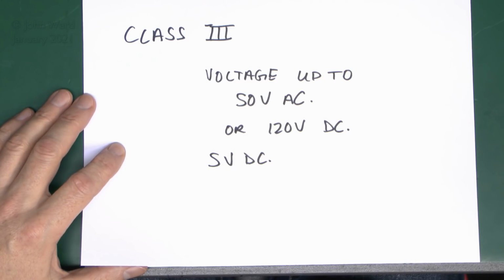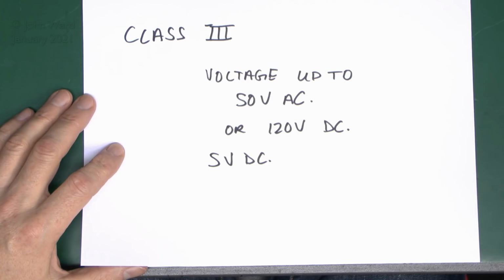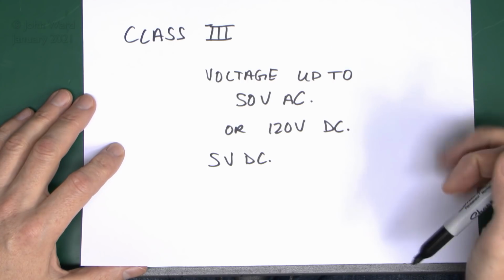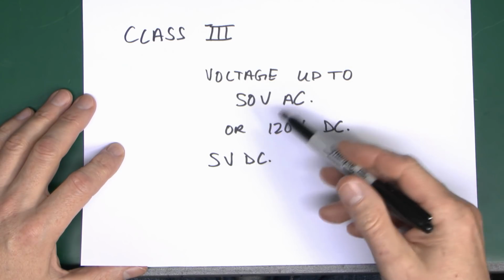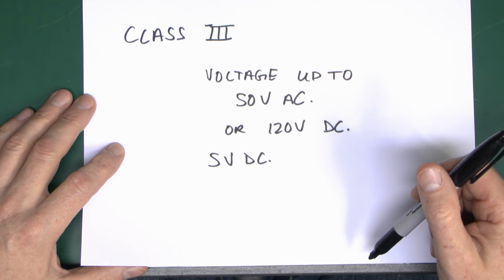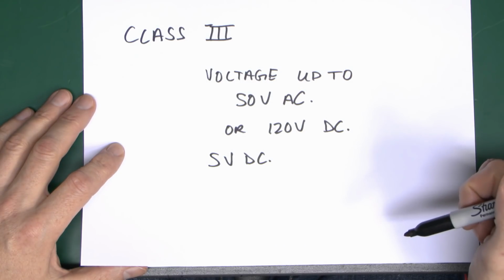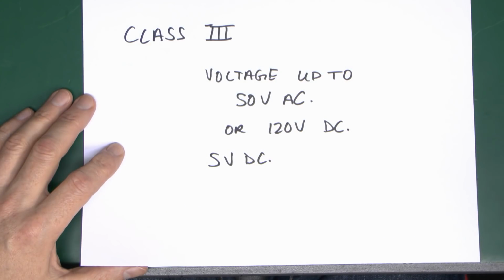It can be in things that you're going to be installing, say things like LED tape, for example, would be a Class 3 item because it has the actual power supply or the power converter unit, and then the tape itself runs at some low voltage of DC. The actual 230 volts gets nowhere near it, and it's separated from that, and therefore there's not a problem. Even if someone came into contact with it, it's not going to cause a shock or any kind of injury.